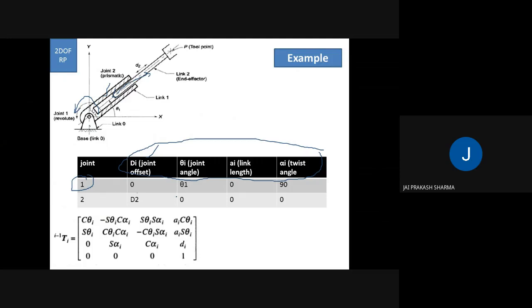I'm not going to explain how we are going to find this. I'm just showing how you can do this. So you have to know or get the information on how you can find these different parameter values. After getting the joint parameters of DH, you have to fill these parameters in this homogeneous transformation matrix which was given by DH, or Denavit-Hartenberg.